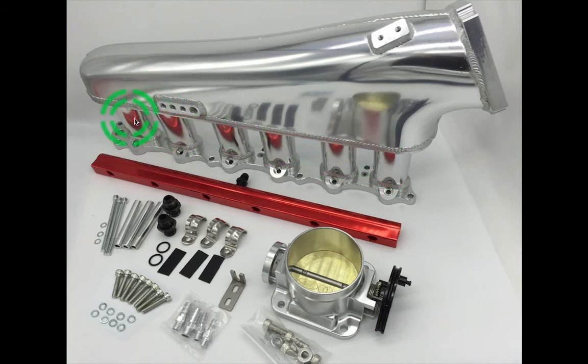So if this one is getting more air, but we are calculating fuel based on the majority of the ports, there will be a slight fuel starvation here, which, if it's slight, maybe is not as bad, but if it's big, then you can call it a day and go look for another engine. Yeah, that's why these cheap intakes should be avoided.